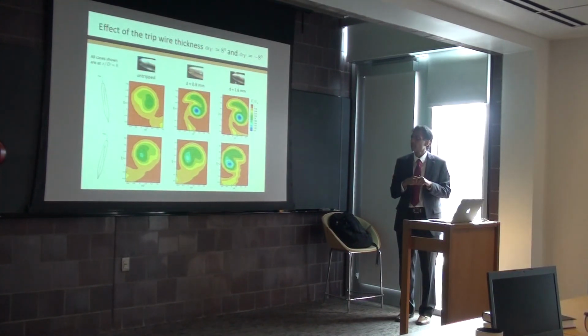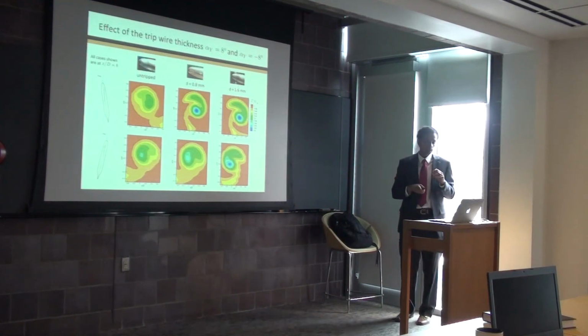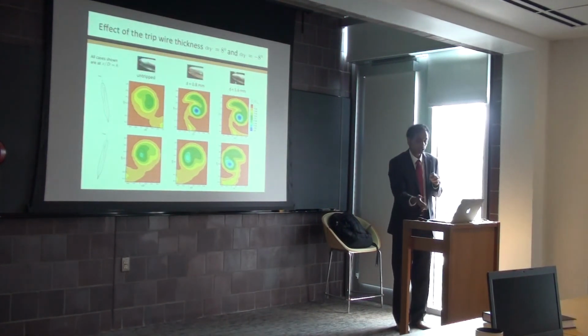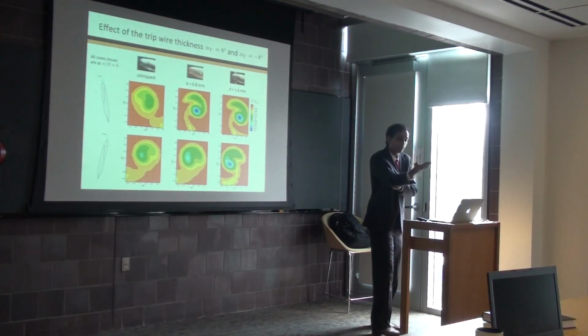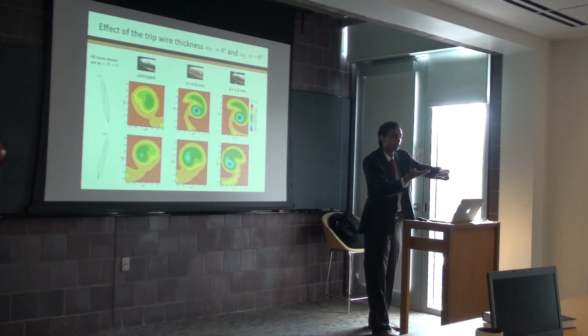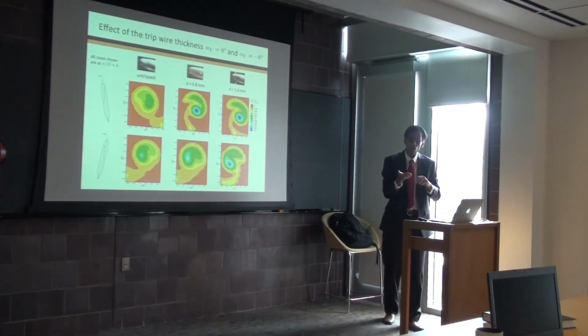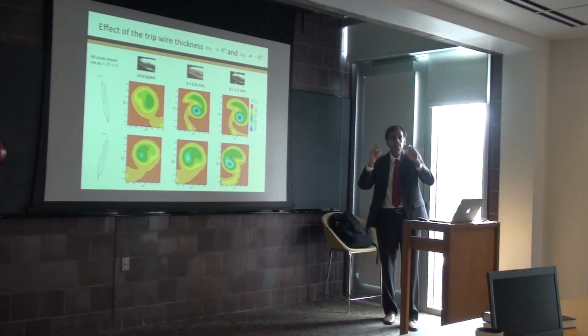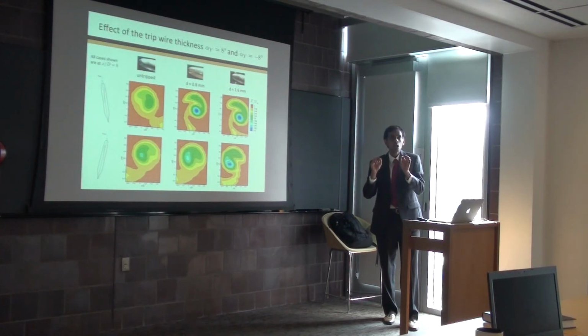The other thing as well is that a previous group weren't interested in the wake. They were looking at surface flow patterns. So they had the body mounted on a sting, and then they took measurements where they put the support on the side, and then they removed the support and took the same measurements again. What they found was that the separation on the clean side, on the leeward side of the body, was unaffected in pitch by the support as long as the angle was not above 15 degrees.